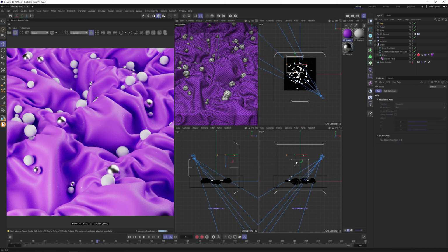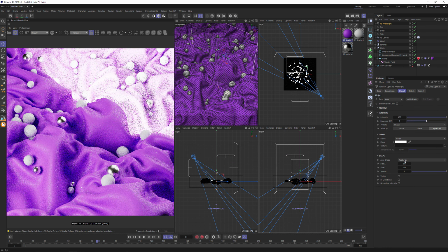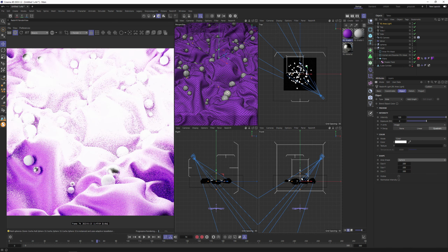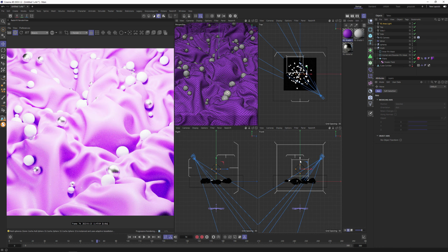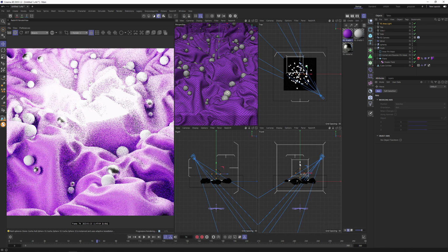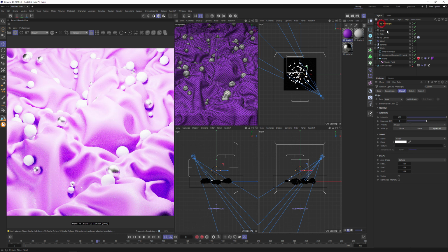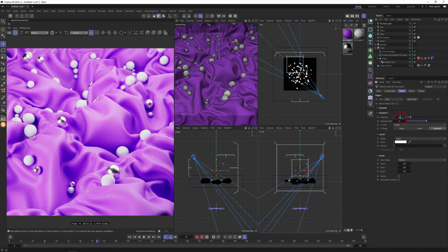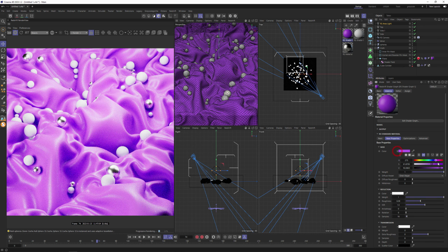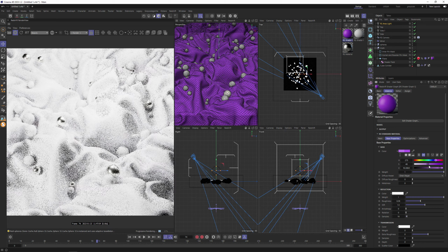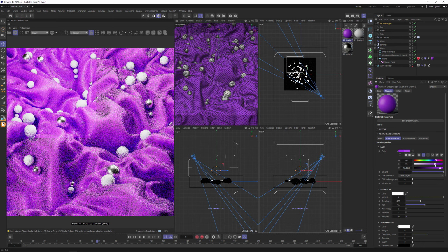The top, moving a bit lower, and create one more area light, but like a sphere, decrease it and put it directly closer to our scene to have this additional specular just in the middle of our scene. Playing with roughness in the material, we need to find the balance, maybe decreasing a bit saturation or checking the high one.